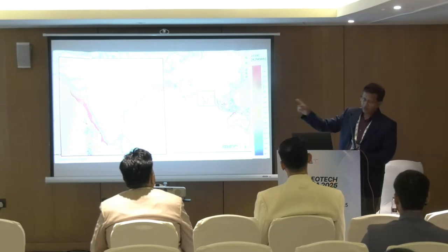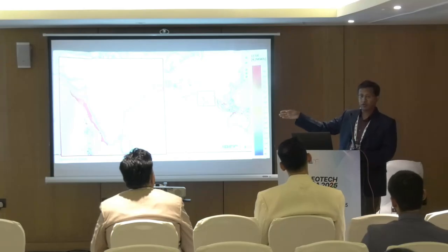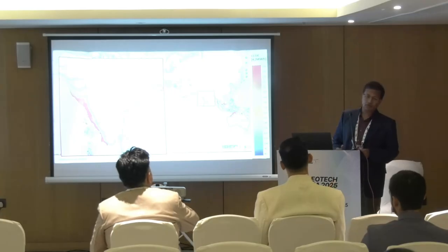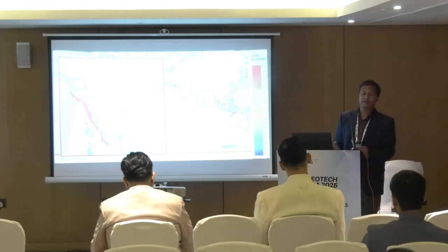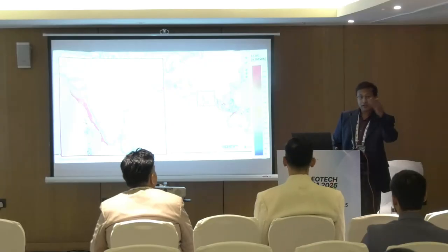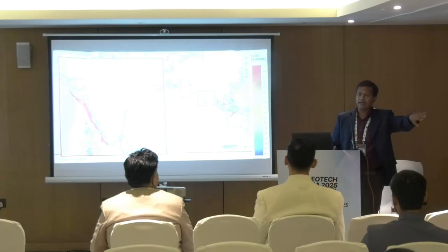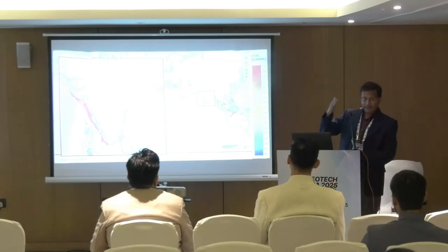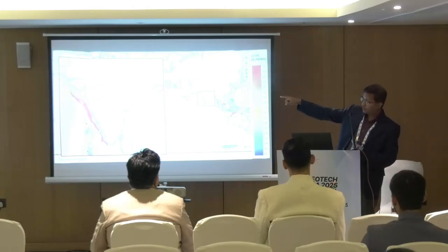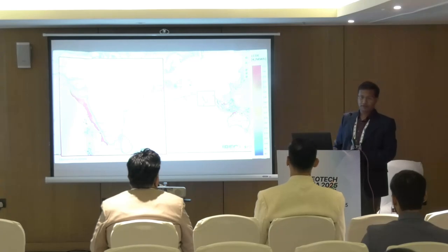So mostly what we have observed at the eastern side, the feasibility of the floating offshore is more because the continental shelf is very narrow. But in the Bombay High and the western side coast, the continental shelf is quite large. So the deep water will be away from the land. That's why the Indian government is presently looking into the bottom fixed type foundations in Gujarat and Tamil Nadu.